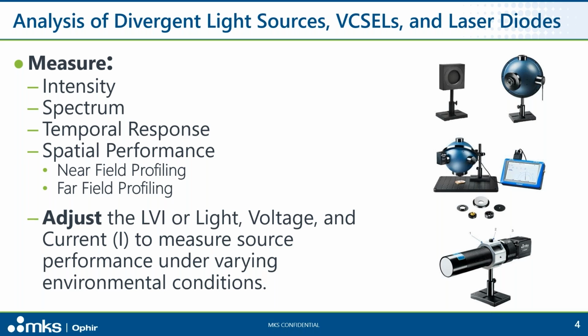Near-field spatial performance profiling tools and techniques include near-field scanning optical microscopy, or NSOM. NSOM is an optical microscopy technique capable of imaging objects with resolution below the diffraction limit of conventional microscopy, or more commonplace, optical reimaging systems based on a microscope objective for near-field profiling.